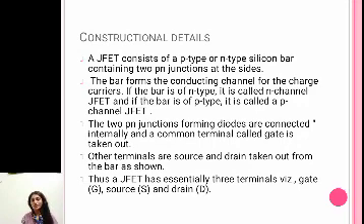The two PN junctions formed on either side, which are basically diodes, are connected internally, and one terminal is taken out from it, that is the gate. The other terminals, source and drain, are interchangeable, so you can make one the source and one the drain, or the other way around. A JFET has essentially three terminals: source, drain, and gate.